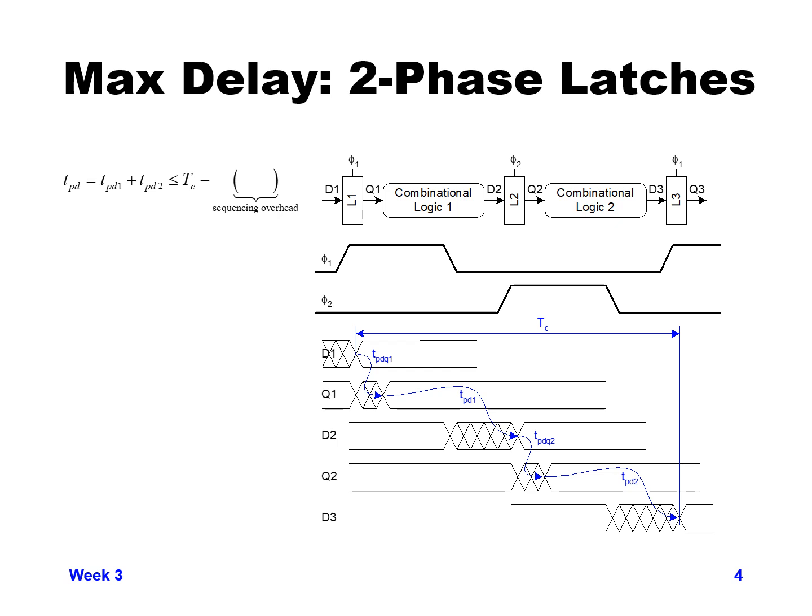The longest of that is your propagation delay, not your contamination delay. So that uses up a certain amount of time. Then we have the propagation delay through combinational logic 1, so TPD1 gets added to our delay time.